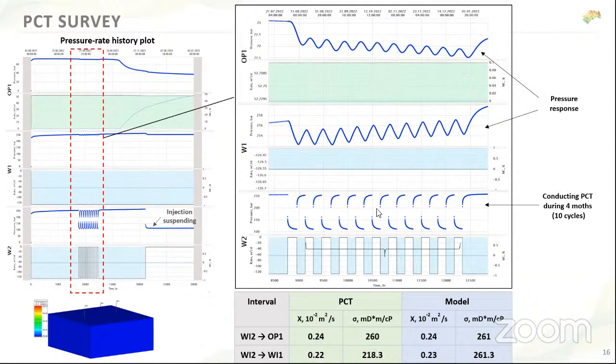To avoid this, we create several pulses, and the more pulses we create, the more reliable the result we get. And the longer the duration of each pulse, the higher the signal response in our receivers. In the model case, we were not actually bothered with that. We just created 10 pulses with the maximum possible amplitude we can, and see quite big pressure responses here. It's up to 2 atmospheres.